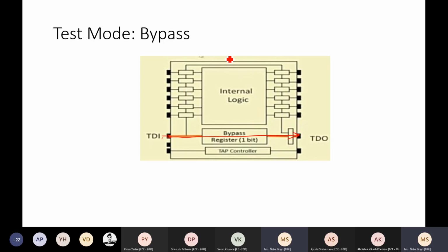अगर हमें इसके through pass कराना होता, pass इसके through भी हो जाएगा, but that will add unnecessary delay because the data will only be shifted at the clock edges. तो अगर यहाँ पे मेरे पास 12 scan cells लगे हुए हैं, so at least 12 cycles will be required to move through all these scan chains, then move to this mux and get the output, which is a waste of time. So directly a dedicated register is required here, which will be enabled only according to the instructions received by the instruction register that can set the mode, right?